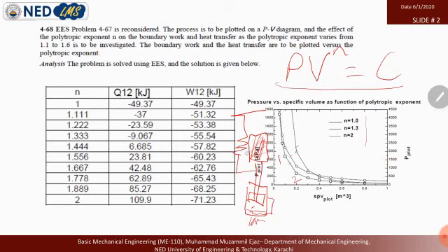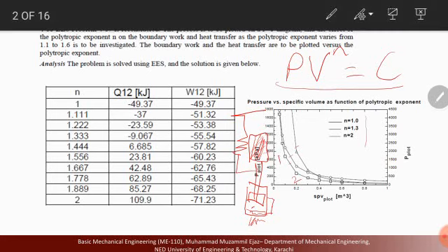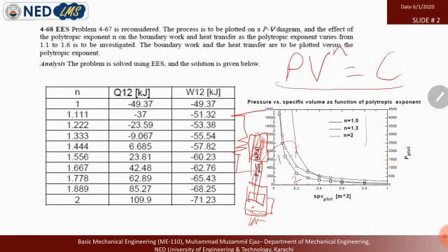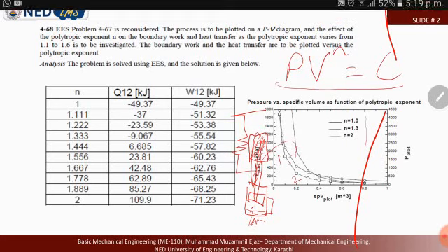Different positions of a spring have different restoring forces, so the force on this piston is varying. It is therefore not called polytropic and will not follow this equation. I would like to remove this confusion in this lecture. Let's move on. I hope you understand the difference between polytropic process and non-polytropic process.